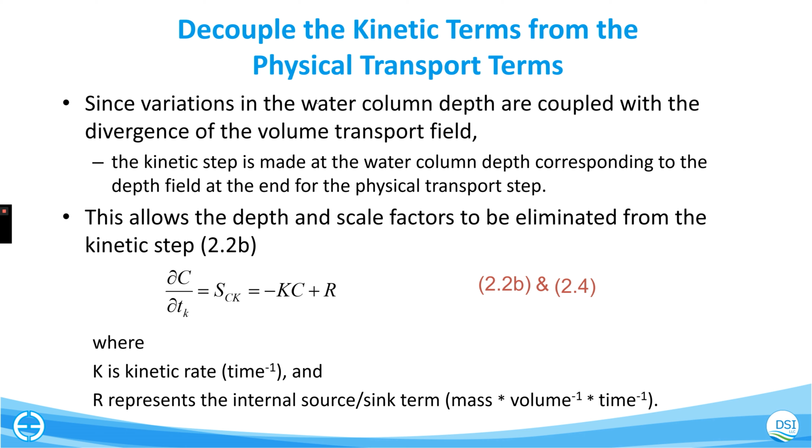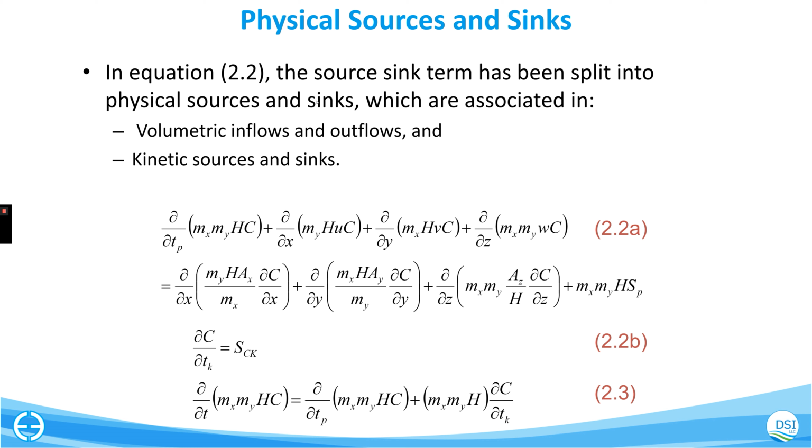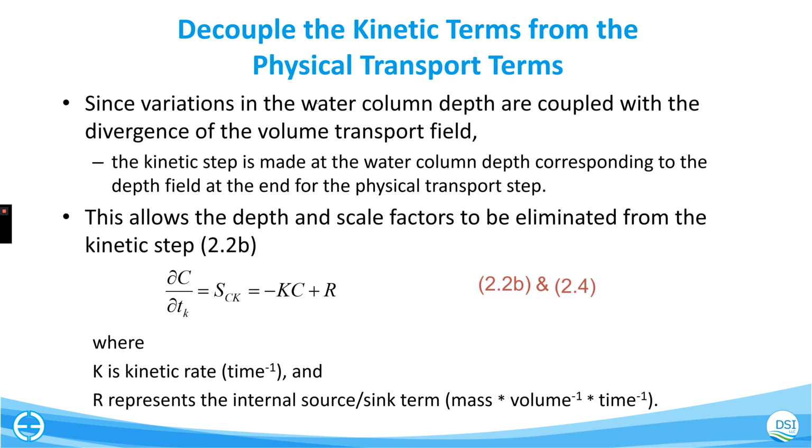So in EFDC Plus, you actually have a kinetic time step. Every minute or every 5 minutes, you solve the water column kinetics. However, every single time step, you are solving the transport equation. So all the material is moving around, being advected and diffused, but only at whatever user specified interval are we doing the kinetic time step, which really helps the computational speed of the model.